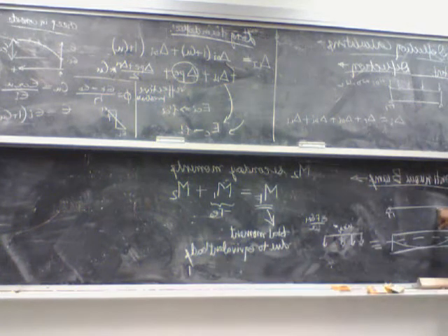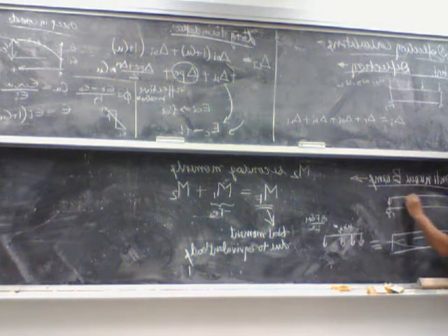So if I'm given this indeterminate beam and I have a parabolic tendon, what I'll do is remove the parabolic tendon, remove the F, and replace it with its equivalent load, which is a distributed load.